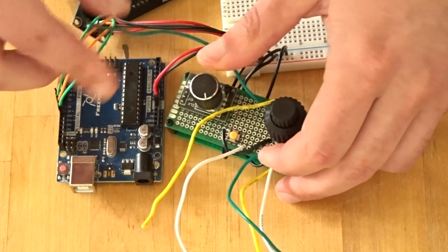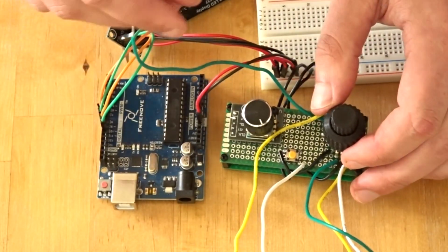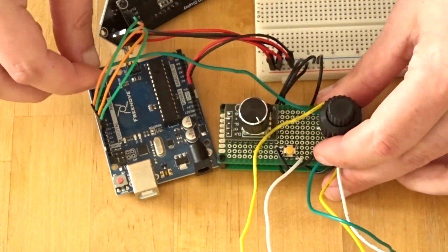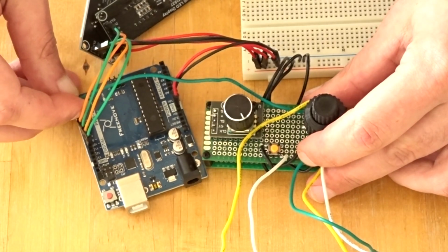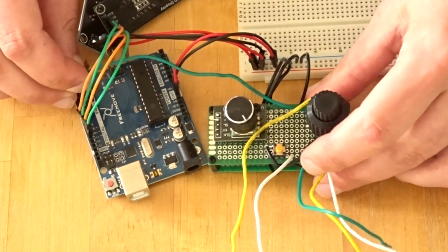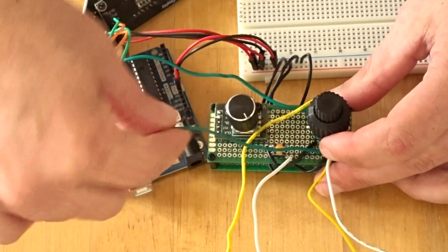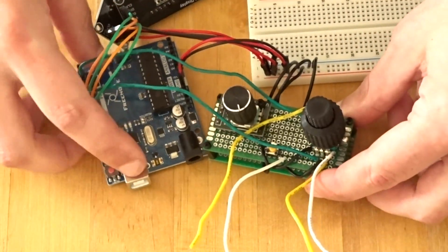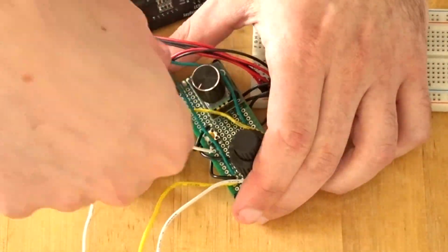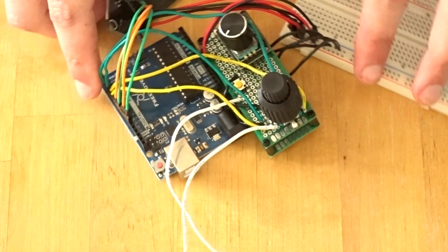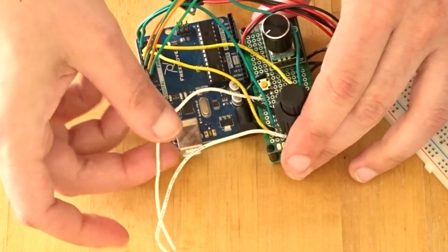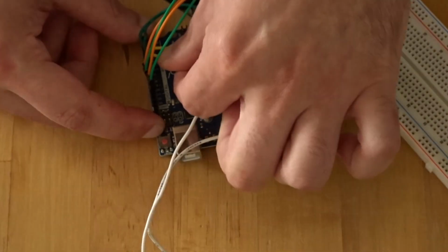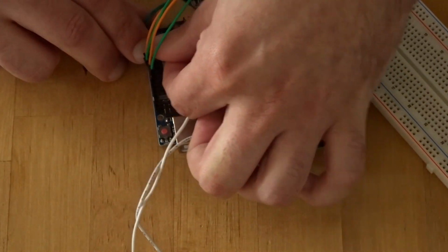Now I'll come back to this later, why it's important, but for now just hook them up in 2 for the inner shaft or outer shaft, then skip a pinhole, insert the A or the same one from the inner shaft or outer shaft, whichever you took, and then skip a hole, and then just fill those holes up with the B pins. Now that leaves us just with the 2 wires for the switches and to switch in the button, and you can put them in any hole you'd like that's marked with a number or an A in front of it.